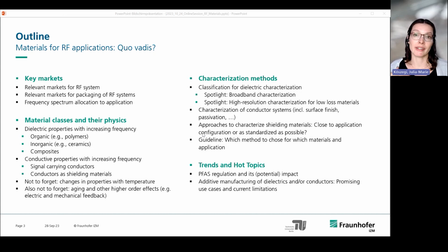We need to talk about characterization methods, again, dielectric, conductive, and shielding. And here we can have a few spotlights on, for example, broadband characterization to get data rather quickly for a broad frequency range versus the characterization of low-loss materials, where you need a very high resolution and need to put an extra effort to that end.